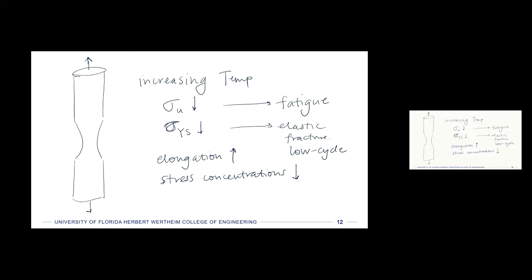So these are kind of like competing effects, right? If stress concentrations are going down, awesome. But at the same time, our ability to withstand that stress is going down, right? Our yield strength is also going down. So unfortunately, we are going to have to use this sort of uniaxial test data in order to interpret things. But we need to somehow at least have these trends in mind because they'll inform some of the ways that we interpret the data at a later time point.